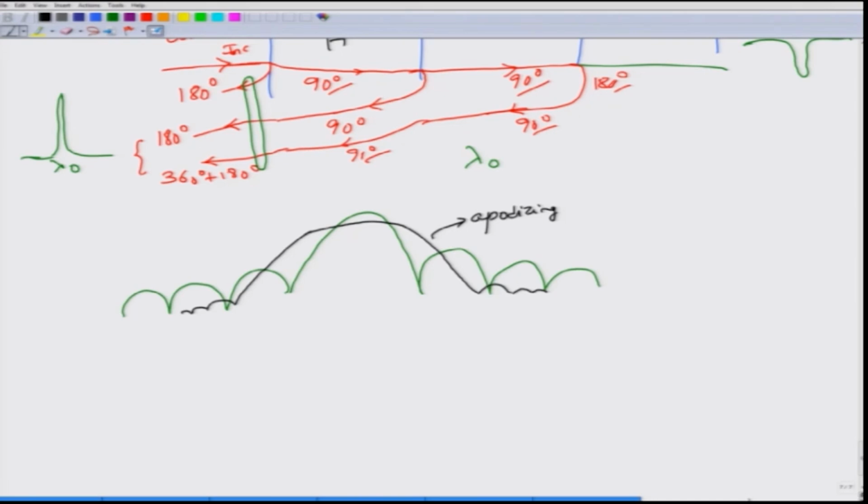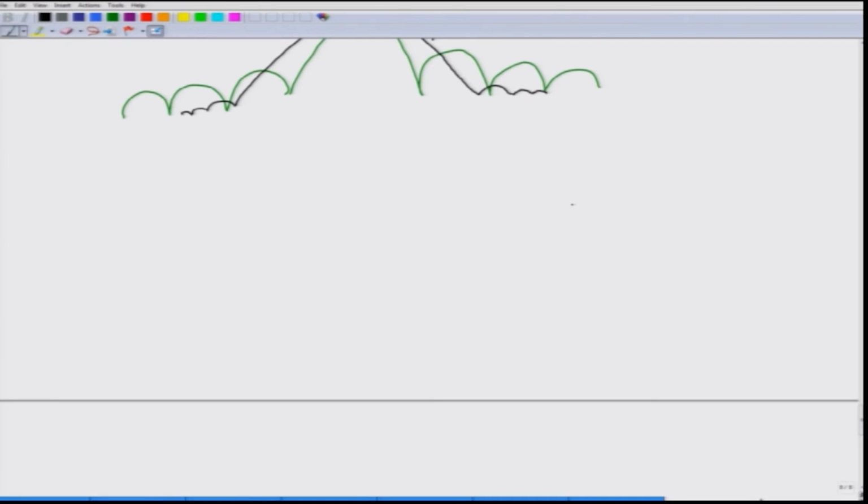There is one more device which is very important for amplifier situations. This is called a long period grating. In the long period grating, you have the core propagation mode coupling to the cladding modes. Cladding modes can be an infinite number of modes, of which you have to pick a particular cladding mode. I mean, the construction actually determines all that picking.